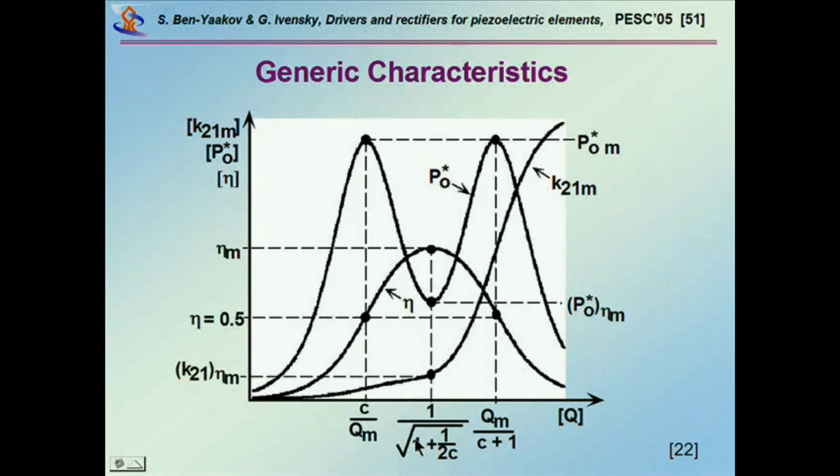The reason is that this is the point where you get a resonance with the reflected output capacitance, and you look at the voltage across a series resonant network. This is, of course, very nice for fluorescent lamps, because you need to ignite a fluorescent lamp. You need high voltages, and before the lamp ignites, the resistance is very high. So you can have very high gain, and then of course you go back to the operating point.